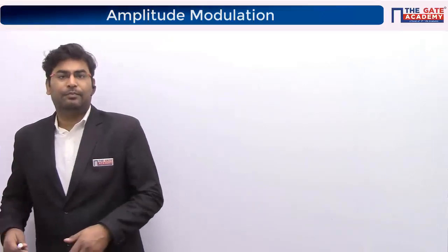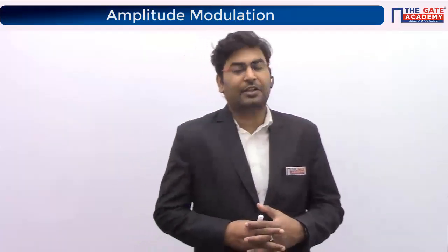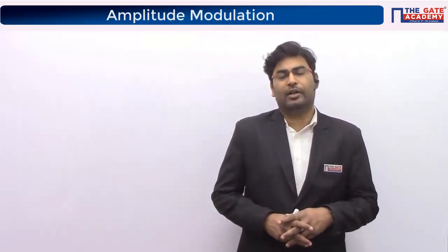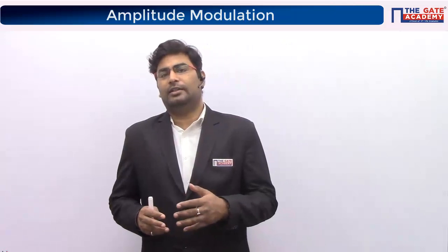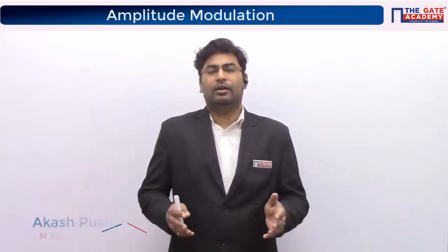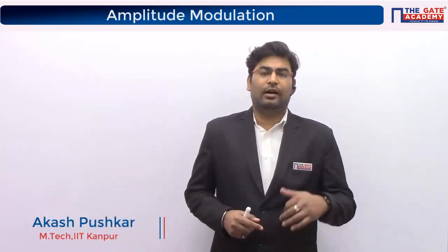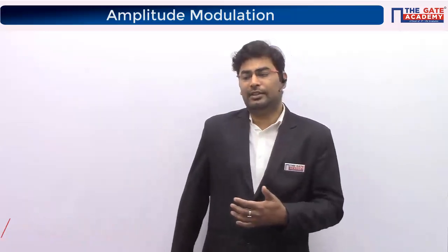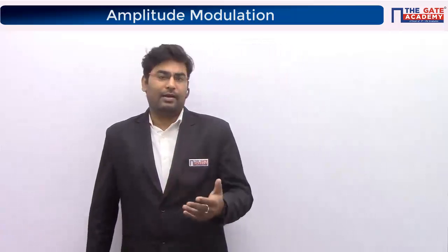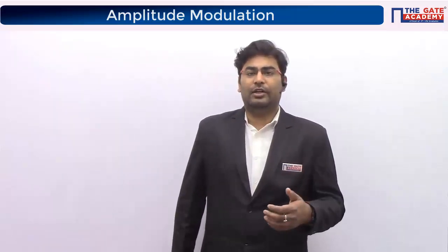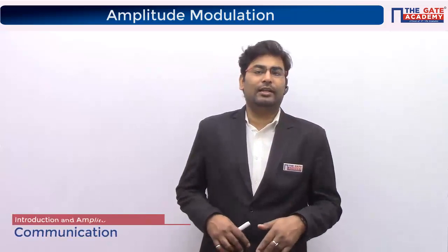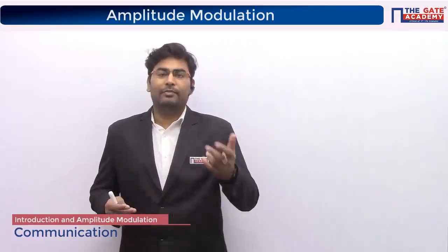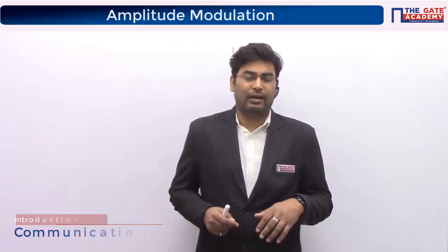So guys, before the recess, we had a discussion on generation of AM signal. We were using square law modulator. So square law modulator is a kind of a block that consists of a couple of things. The important thing is your nonlinear device, which we saw as a diode in our circuit, and after that we have a band pass filter. Now we are going to study how we can demodulate the received AM signal at the receiver end. So we need to get back the message from the AM signal as well.